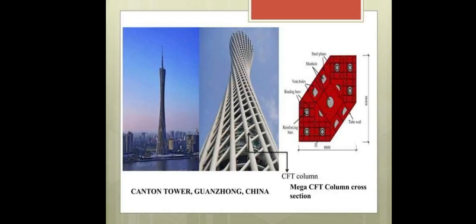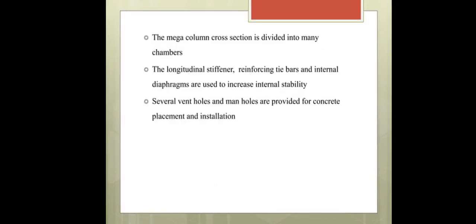These holes are generally provided so that while filling the concrete in the steel tubes, the volume change and air bubbles which are generated can escape.